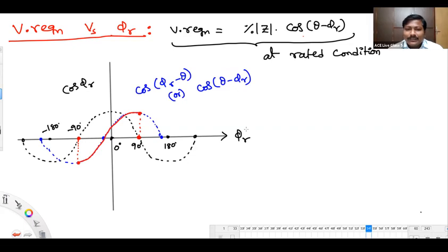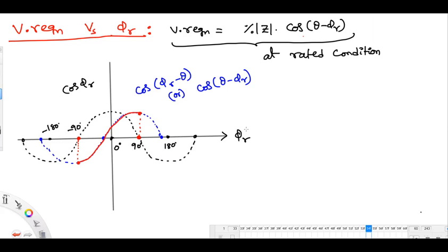Tell it again, please. Cosine of angle between voltage and current, you said. Yes, sir. Who will decide this current value? Voltage value, let's say source. Who will decide the current value? Based on the load. Power factor means cosine of the angle between voltage and current. That's okay, but current is not going to be decided by your line impedance. It is decided by your load. Okay, sir.